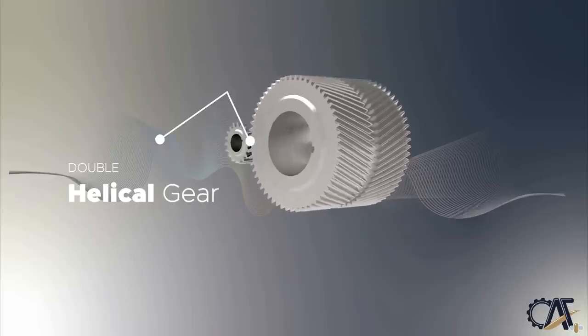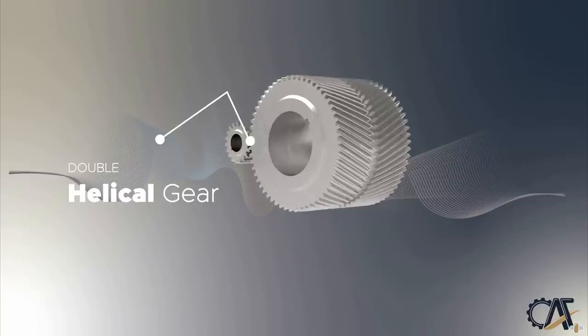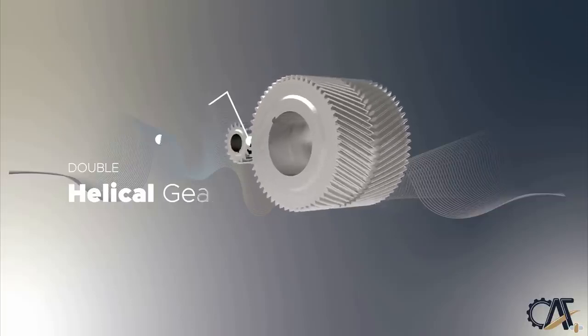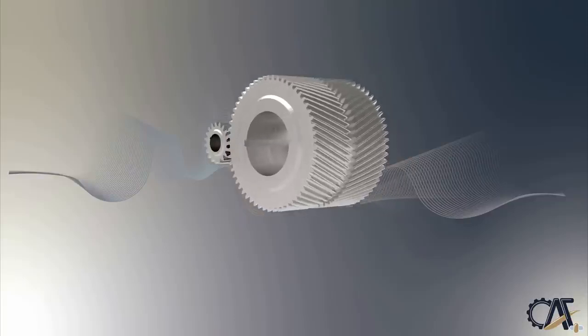On the other hand, helical gears have sliding contacts between the teeth, which in turn produce an axial thrust of gear shafts and generate more heat. So this makes them less efficient than spur gears due to tooth slippage.